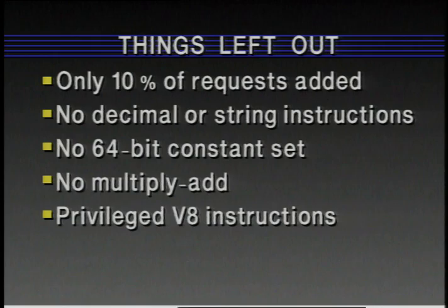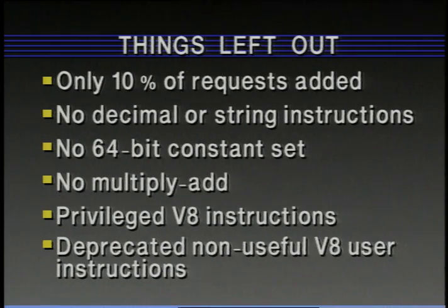Initially, I suspect we'll provide compatibility by doing hardware implementations of these instructions, but in the future we may implement these instructions in software. And so we have noted a number of version 9 instructions as being in the category of deprecated instructions. For these instructions, it's suggested that you try and avoid using them so that in a few years these instructions will tend to disappear from the binaries of programs. One example of a deprecated instruction is the 32-bit multiplies. The 64-bit multiplies completely supersede these instructions, and there's really no need for the old 32-bit multiplies.